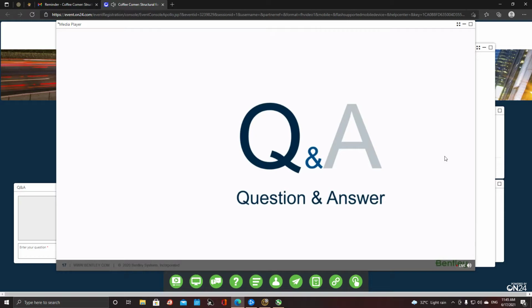Which code can be used to design steel tanks? This webinar is mainly for concrete tanks, and for steel tanks, StaadPro has steel design codes. You can use any code that you wish, Eurocode or American code, to design the steel members. StaadPro is already good at designing steel. It's just the concrete walls and slabs which were lacking in StaadPro, which we filled in the latest version. For steel tanks, it's already good, but we still do not have the steel plate code check. For steel plate code check, we need to use a spreadsheet to design. But for steel members, we can easily do that in StaadPro.